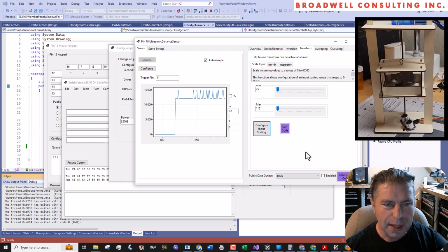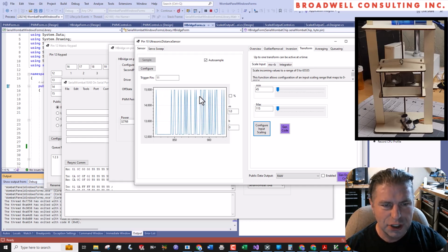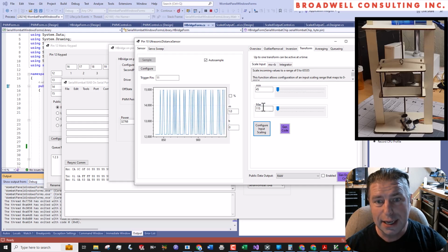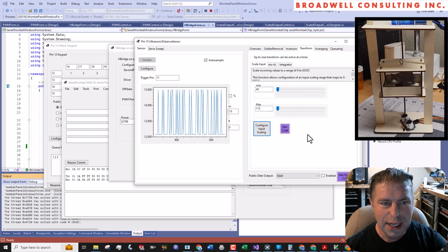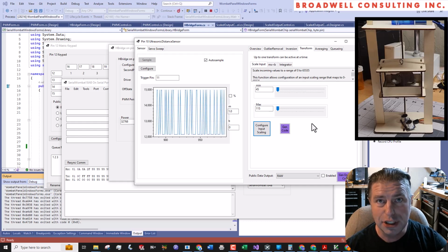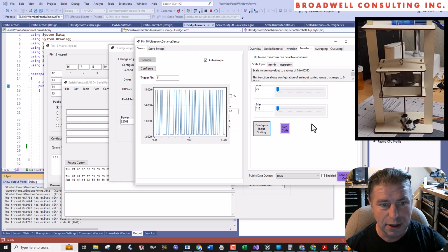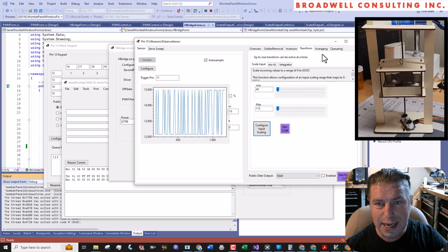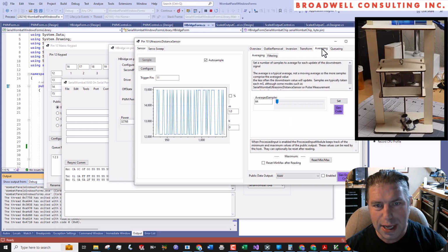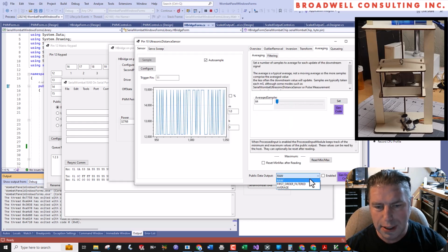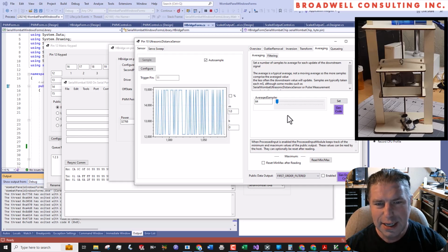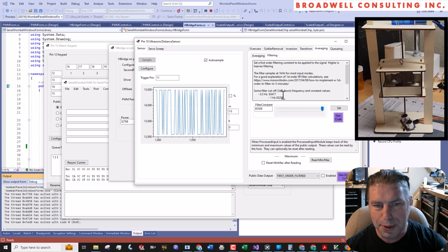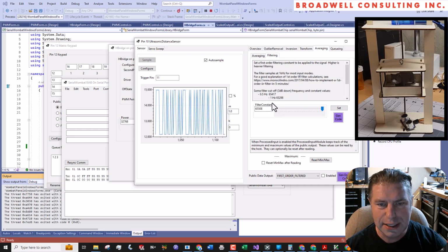As we get closer, we also see, boy, there's an awful lot of jitter in this signal. So that sensor is limited in its resolution, and also because the Serial Wombat chip detects in 17 microsecond intervals, there's also some quantization going on there. So let's go ahead and, I think for this one, filtered makes sense. We're going to want to control on this and maybe not aggregate a whole bunch of samples. So we'll put in a filter on this.